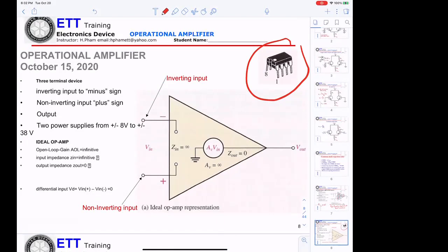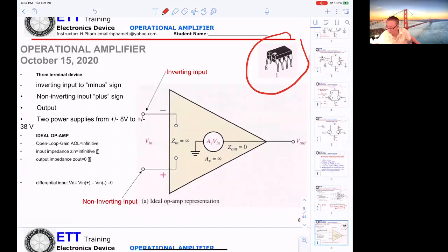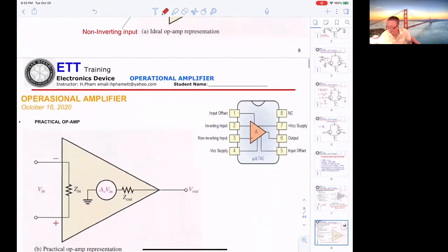We don't use 1 and 5 either. When you're working with circuitry including an op amp, you must be careful. They're using 15 or minus 15, or 12 or minus 12 volts. If you're not careful, it can be cooked.